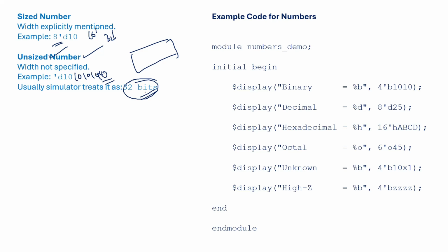If you don't specify anything, it will take up to 32-bit by default. Infinity numbers also you can represent. Usually unsized numbers are not the professional way, so most of the time we will use sized numbers only.